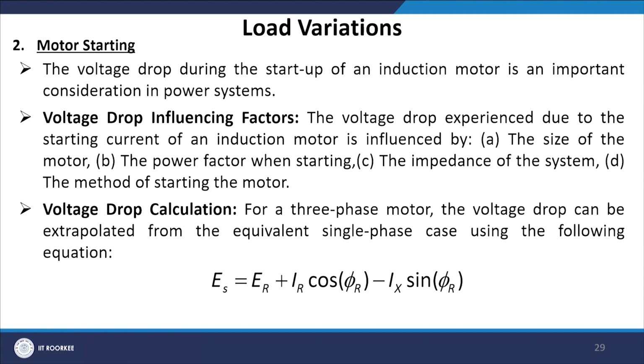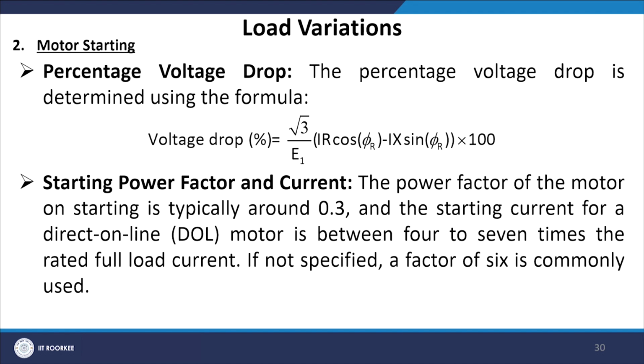The voltage drop during the startup of an induction motor is an important consideration in power system. The voltage drop experienced due to the starting current of an induction motor is influenced by the size of the motor, the power factor when starting, the impedance of the system, and finally the method of starting of the motor. For a three-phase motor, the voltage drop can be extrapolated from the equivalent single-phase case using the following expression.